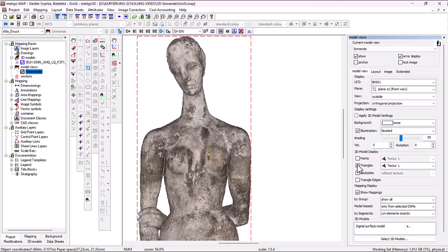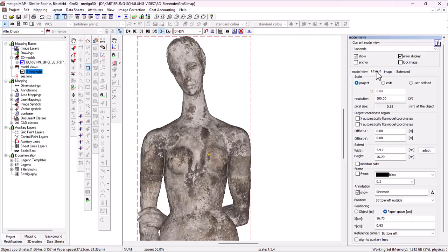We switch to the second card layout. And the upper area is interesting because I can later correct the display scale or can also combine model views with different scale sizes. The way it works in 3D mapping is that I load an SFM model, for example a textured surface model, true to scale into the project. And when I map in the project, the quantity survey takes place on the 3D model.